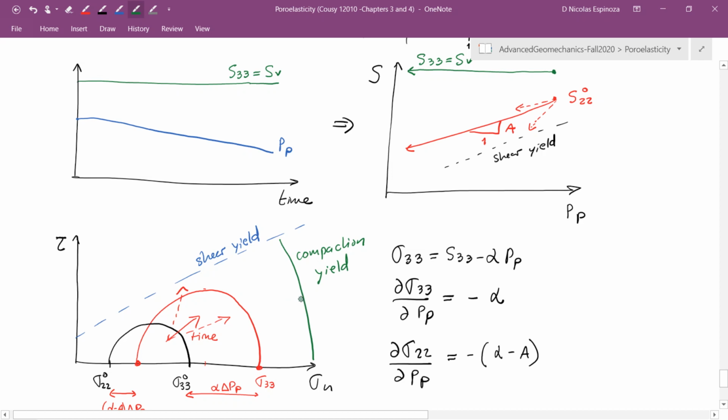Okay, this is when you get to the compaction yield, when you get into significant volumetric strain, significant losses of porosity, significant subsidence, and problems with casing shearing on top, or casing buckling in the reservoir, and that is something we're going to talk a little bit more about in a bit.